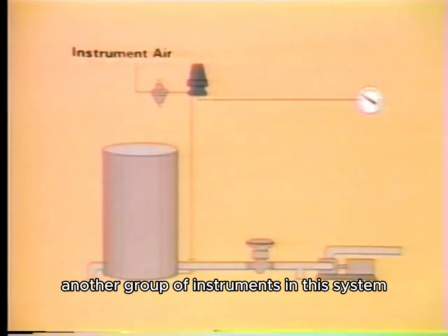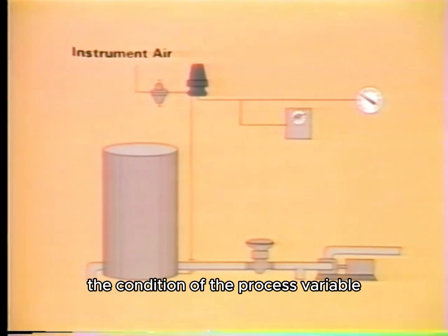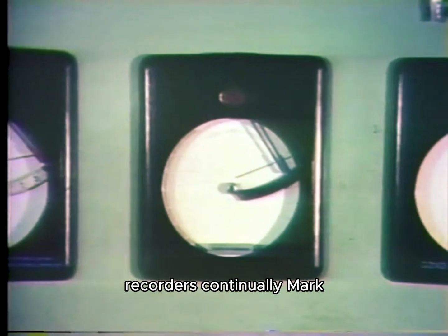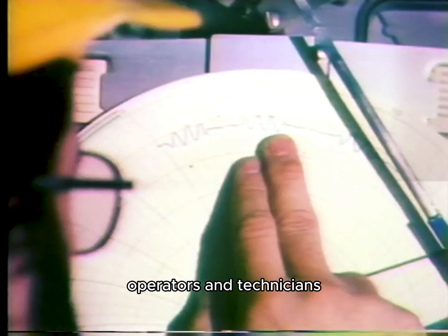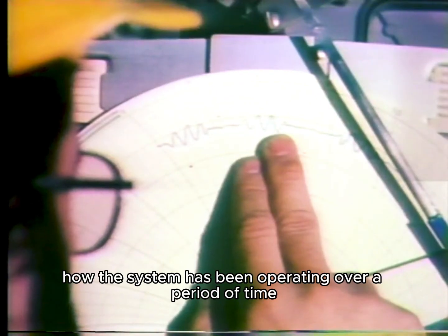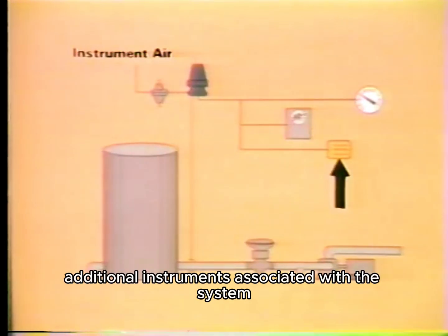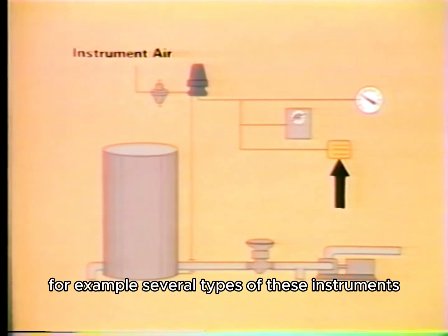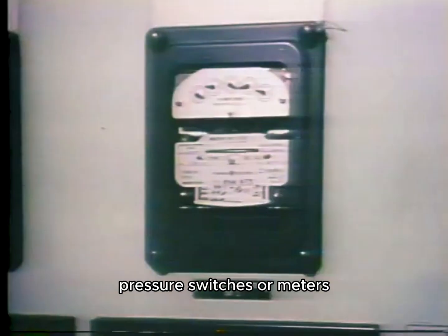Another group of instruments in this system are recorders. Recorders are devices that not only visually indicate the condition of the process variable, but also maintain a constant record of the process variable. Recorders continually mark or record the condition of the process variable on a chart. Operators and technicians use this chart to see how the system has been operating over a period of time. Often there are additional instruments associated with a system that provide several different functions. For example, several types of these instruments that you may be familiar with are alarms, pressure switches, or meters.